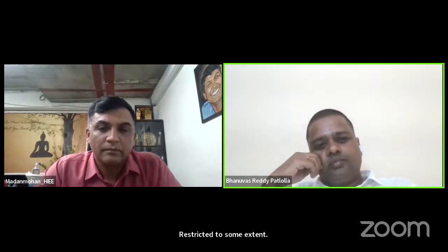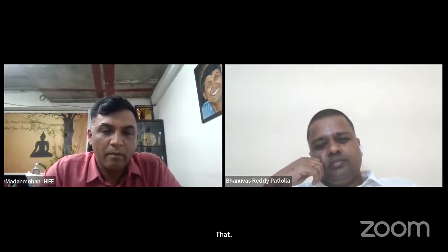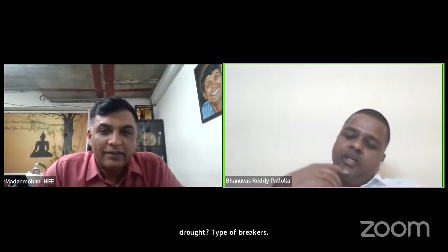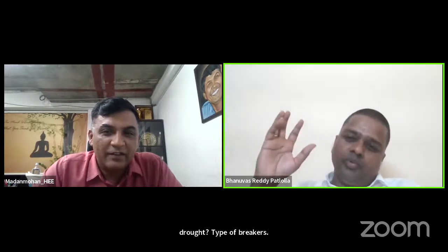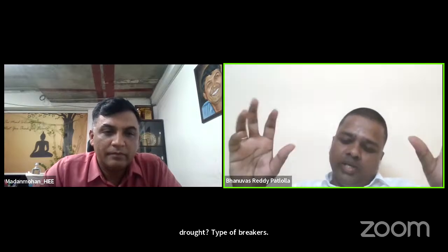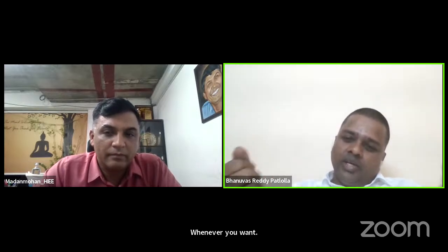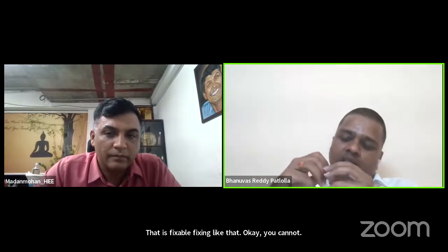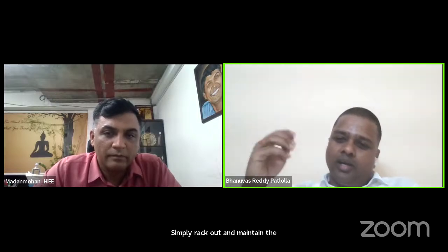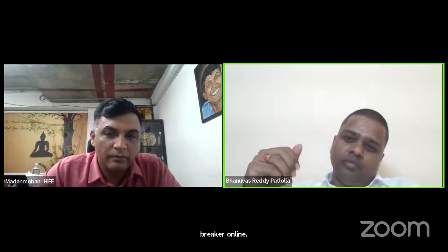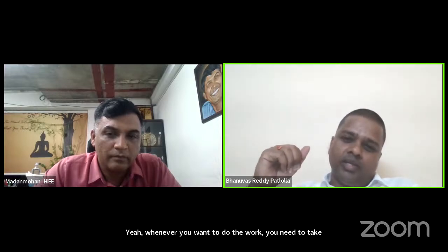There's a question from Akash Babu: what is drawout and non-drawout type of circuit breakers? Non-drawout means some breakers are only fixed type. You cannot draw out the breaker whenever you want. You cannot simply rack out and maintain the breakers or service the breaker online. Whenever you want to do the work, you need to take a shutdown of the breaker. Then only you can repair the breaker.